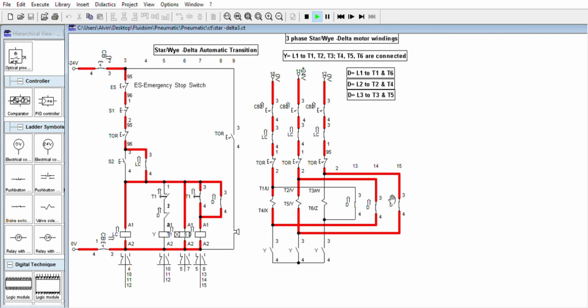You can close the transition by having a power resistor or sets of resistors to keep the circuit closed while the delta contactor is turning on. So there is no chance of open circuit here because we always connect the power resistors.